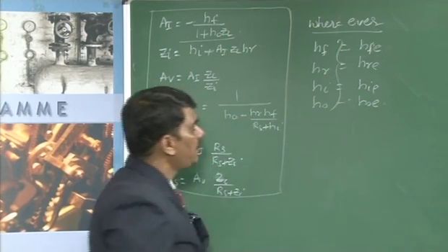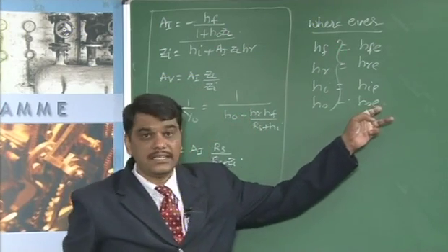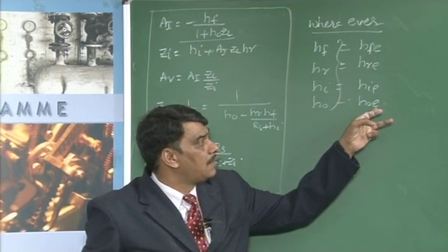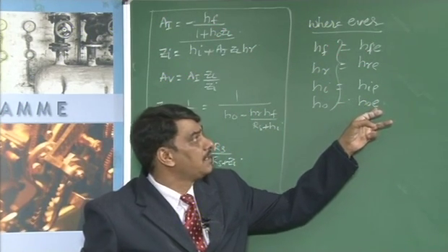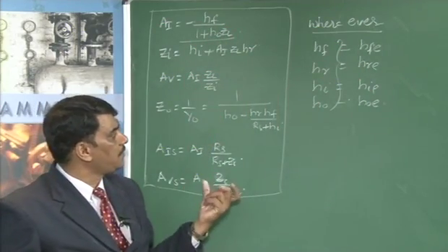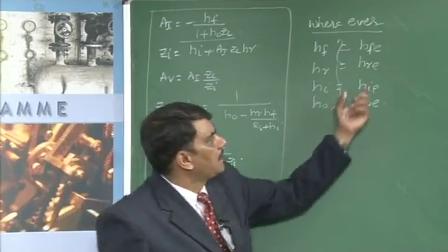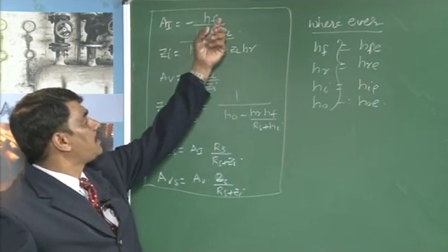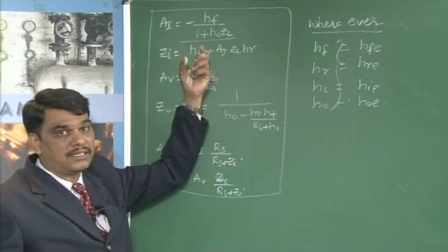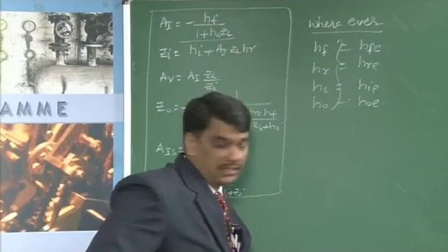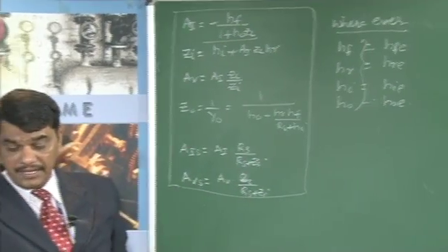And similarly, the second suffix indicates the corresponding configuration, means the E suffix is indicating a common emitter configuration. If E is replaced with C, in this case the same equations are useful for the determination of a common collector configuration. If B is used as the second suffix, then you are going to get a common base configuration.